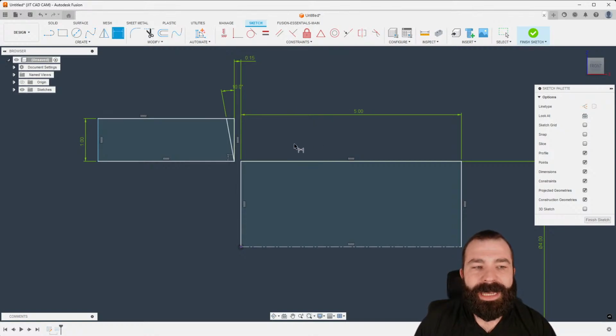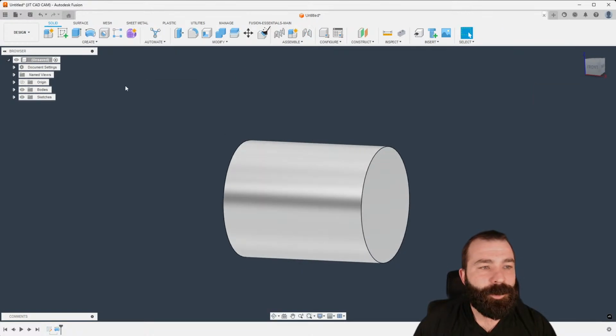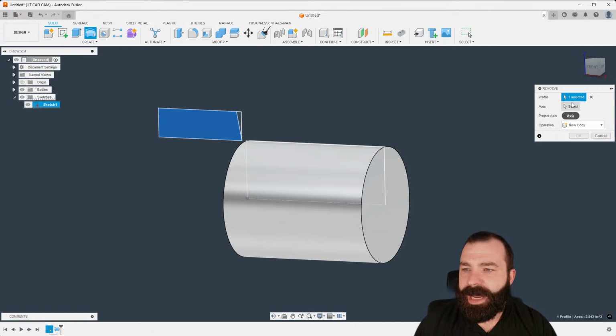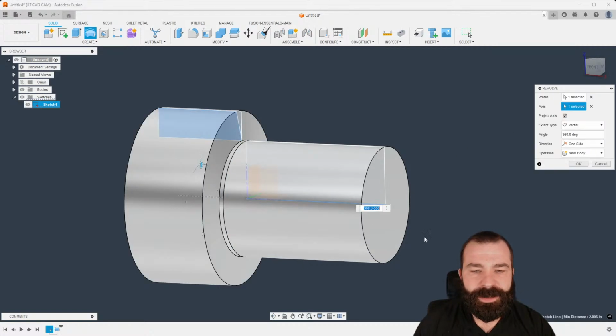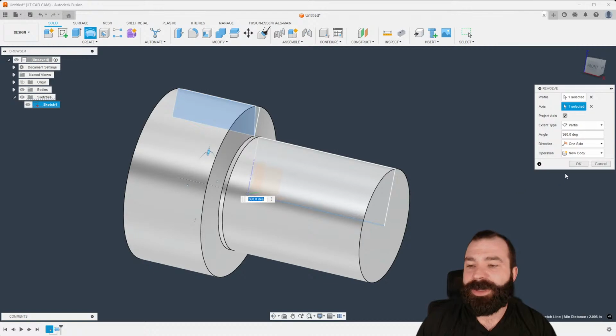Now again, a rinse and repeat. Let me get a few more dimensions on here real quick. If there was a length to that actual collet, you can see here I'm plugging that info in. Again, we're going to do another revolve here using that same sketch, and we have our center line over here from when we drew everything. As you can see, that is basically going to be that collet holding on to my stock.